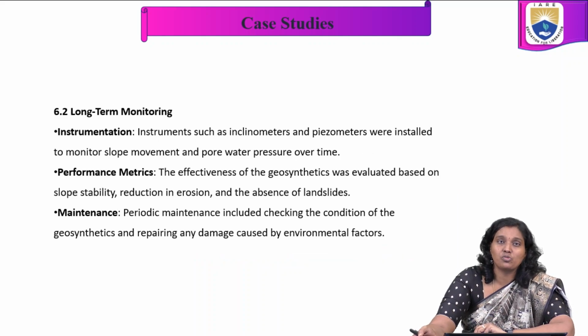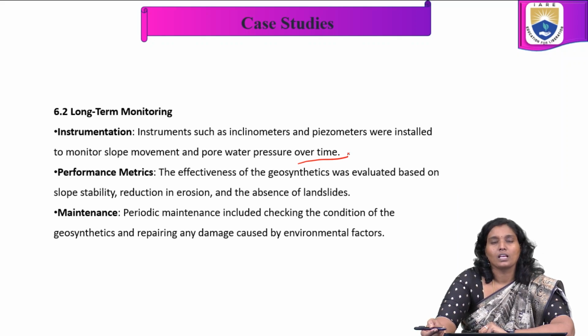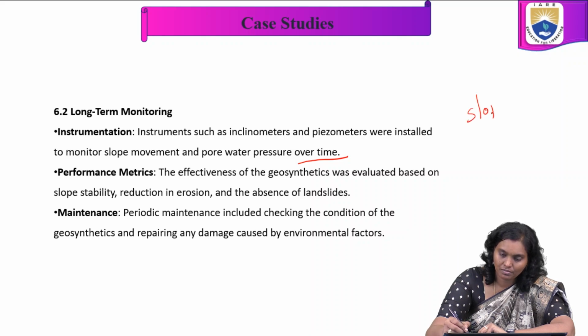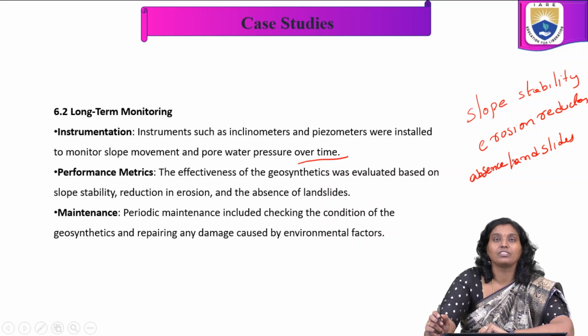In long-term monitoring: instrumentation, performance metrics, and maintenance. Instruments such as inclinometers and piezometers were installed to monitor slope movement and pore water pressure over time. For the performance metrics, the effectiveness of the geosynthetics was evaluated based on slope stability, erosion reduction, and absence of landslides.